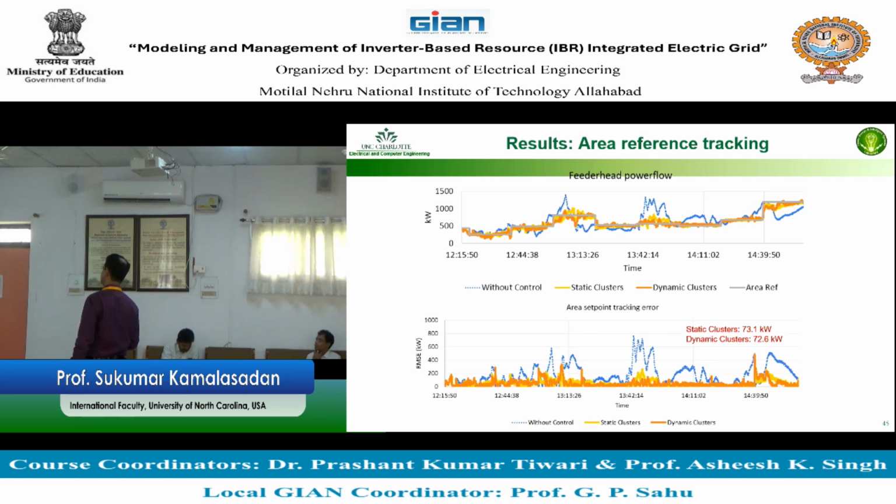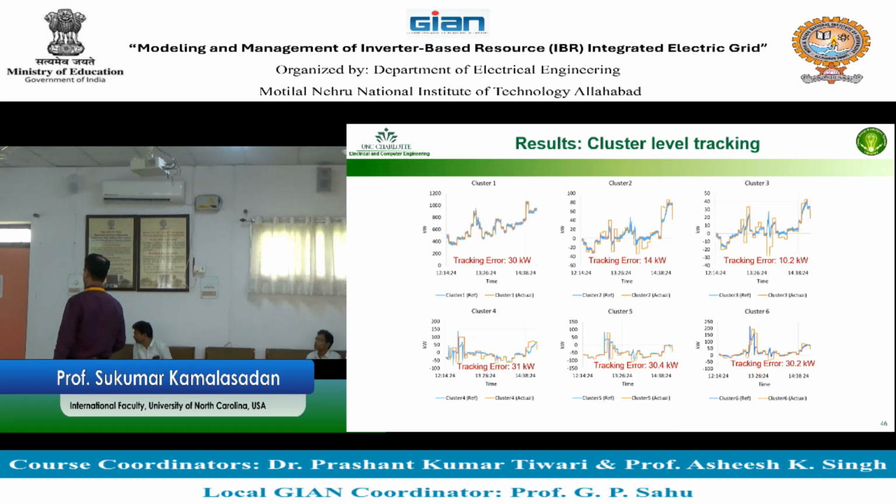And you are asked to deliver the power from the PV battery combination to honor the set point. This is the PV output without honoring the set point, the blue. The goal now, using clusters, is to honor the set point and at the same time reduce the error to 0. Now you can see who is contributing to the set point.